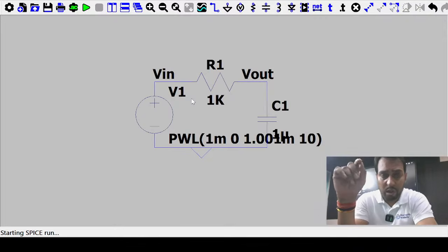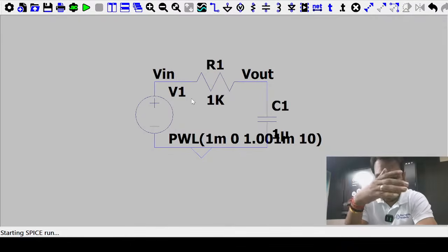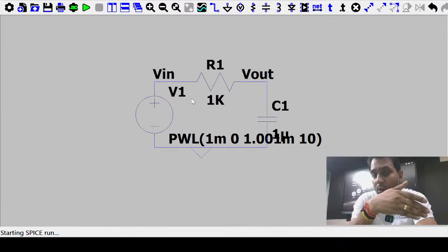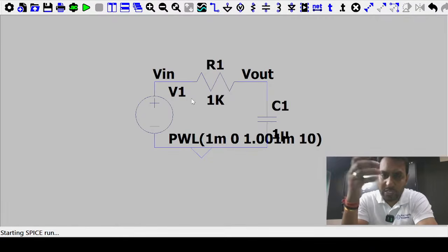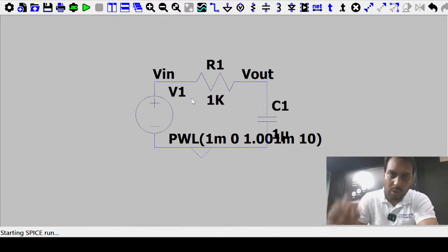Once we go for the MOSFET, we will find the DC operating point, where you set your MOSFET in the saturation region. That's why this is required. DC sweep basically means the input voltage sweeps from 0 to VDD, and you see what the output voltage is. You can sweep the voltage, and you can sweep the current also. AC analysis is simply in the frequency domain on the x-axis. So we have different analyses, and on the basis of that I deliver what is happening.